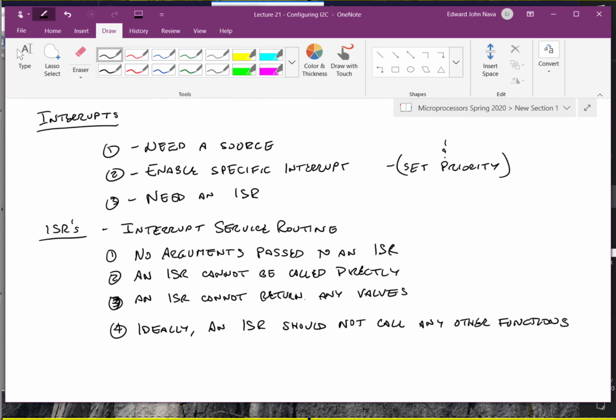So if I look at my disassembled code, if I had a macro instruction that would talk to a port, basically what I have is an instruction moving data to that SFR location. It's basically substituting the equivalent code for the function call.